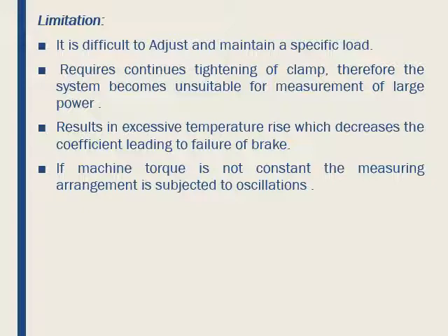Due to heat generation, the temperature rises, resulting in a decrease in the coefficient of friction. Hence, a cooling system is required. When the driving force on the shaft is not uniform, this type of dynamometer is subjected to severe oscillations.